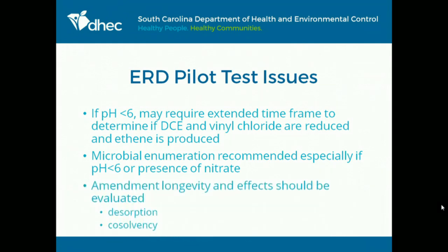And again, you want to look at your amendment longevity in the subsurface. If you're using molasses versus oil, your molasses is going to be eaten up pretty quickly. Your oil is going to last forever and gum up everything in its vicinity. And the desorption and co-solvency are, again, two things that happen when you're looking at reductive dechlorination that can be looked at during the pilot test, which is a lot better than looking at it full scale.